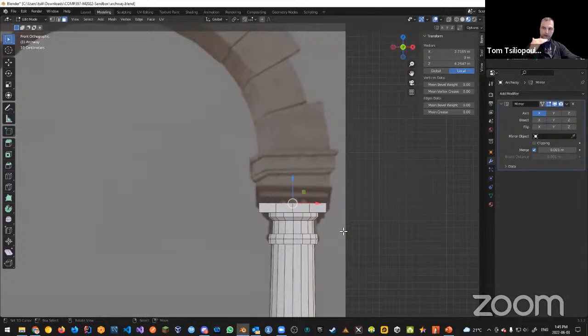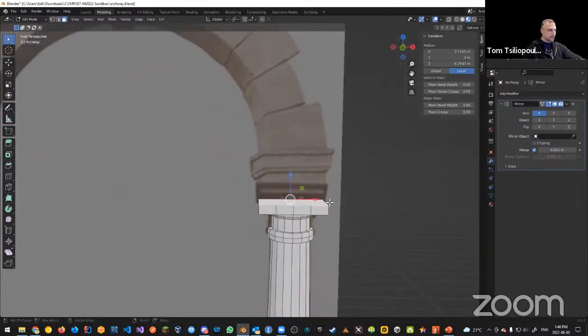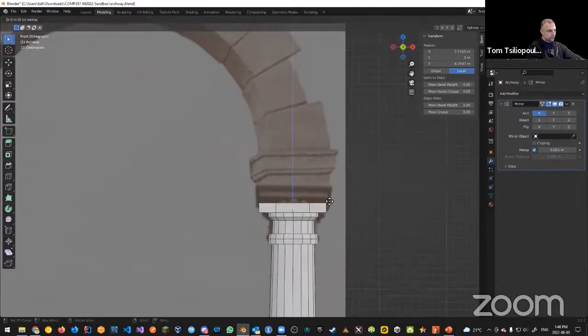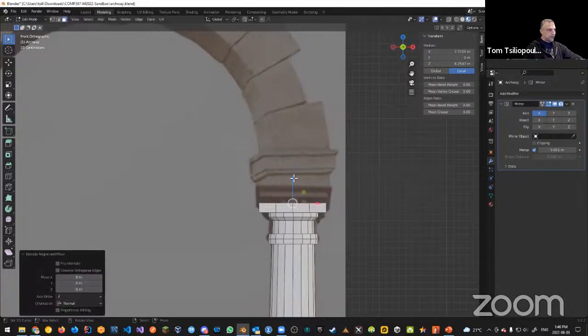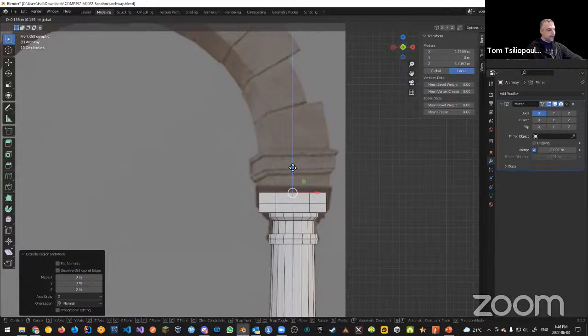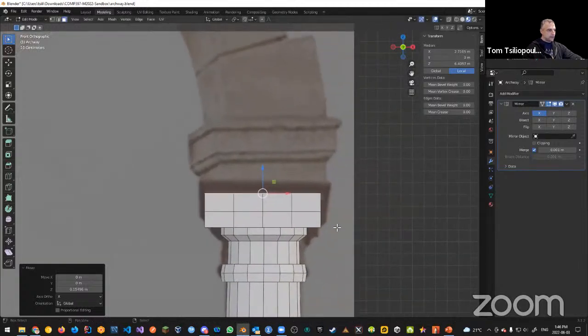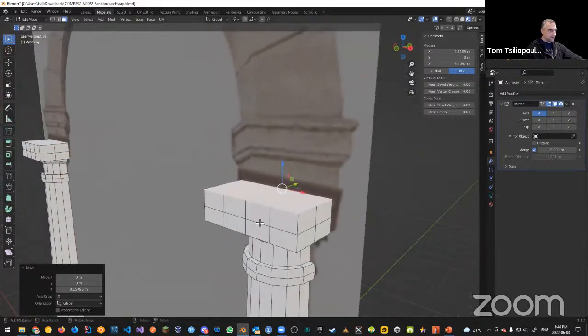And again, I want to extrude up a little bit, kind of make it bigger, so scale out and keep going up and angling. All right, so let's try this first. We're going to go up straight first, but we're going to make it so that it's bigger. So first I've got my face selected and I want to say extrude and then enter. And then I'm going to pull up. So you can see I've got extra geometry there, right? And if I do all this, you can see I'm getting my extra geometry on the sides, which is pretty good, if I want it.